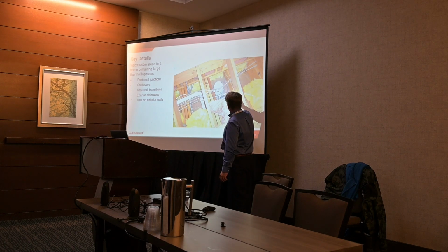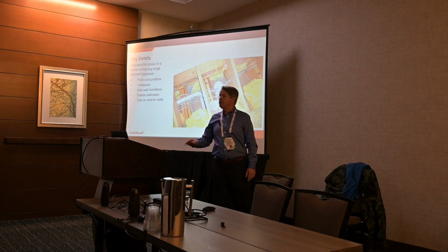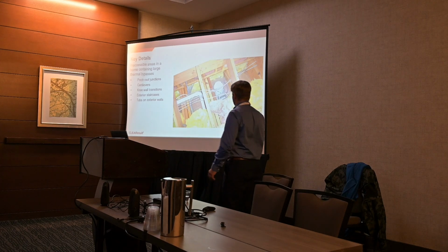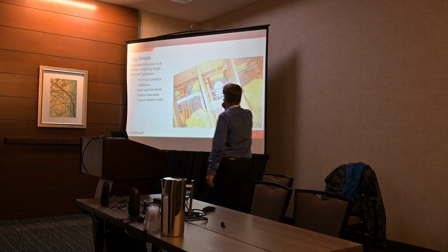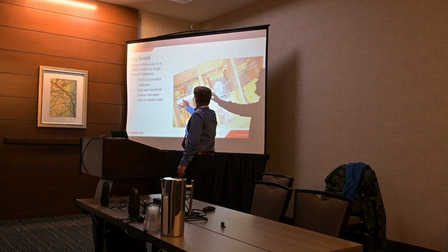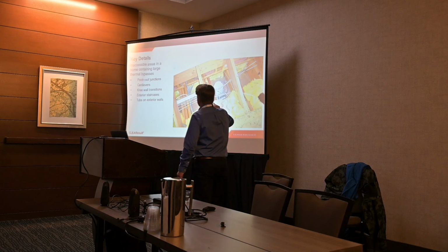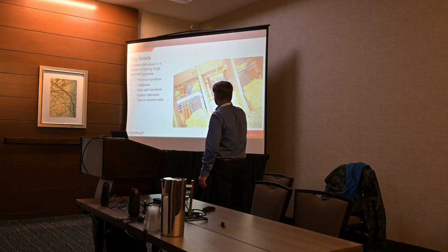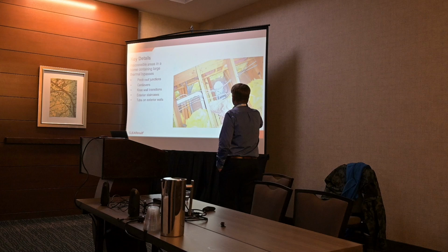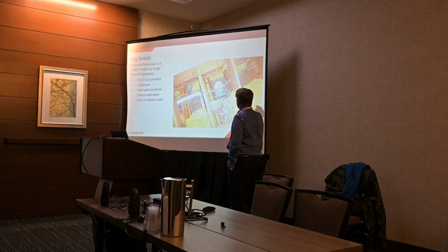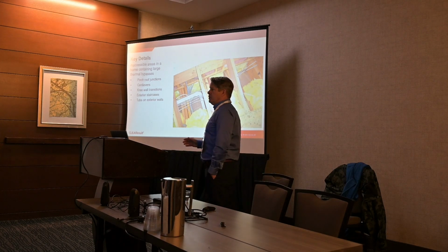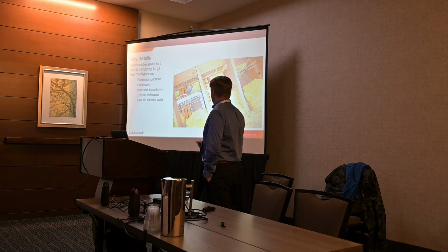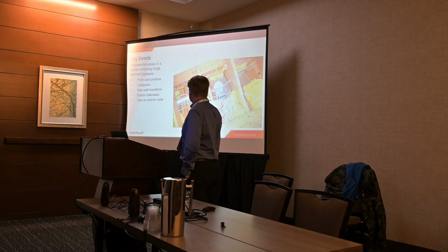And then here we can see the transition, right? Those are the floor joists of the second floor, and there is no blocker in there, which means that the air that flows up into that space goes back and forth between the floors and obviously robs it of R value, okay? Those are the sorts of things that we're looking for. What are called key details, right? So things like cantilevers, knee wall transitions, porch roof junctions, they're hidden details of the house that if we don't address them and make them tighter and better insulated, then a lot of the work that we do trying to make the house tighter never really helps, right? We have to address these sorts of key details.